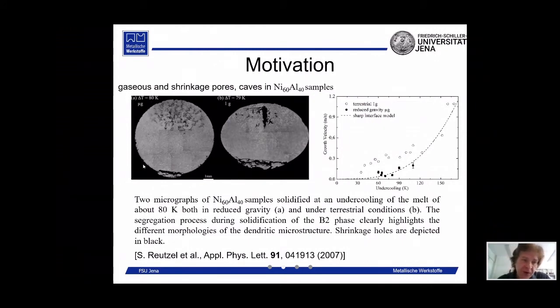In the other case, we have a very weak electromagnetic force, which we need for levitation. Because of this, we have an almost spherical shape of this droplet. In this case, we have a big shrinkage area, big shrinkage defect, porous, but the bottom part or middle and bottom part of this droplet is rather dense in comparison with the microgravity processed droplet. So we have distributed pores in this case and a not dense microstructure.